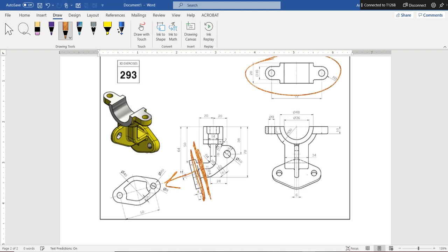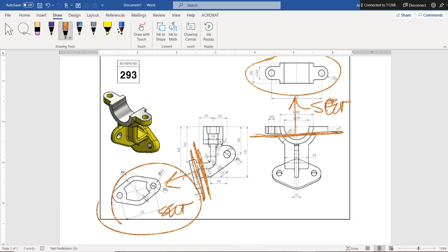Ditto with this thing. This thing should have some type of sectional to tell me that this is only useful when it's a sectional view, okay? A sectional view. Both of these are really sectionals, which are referred to as auxiliary views. They're views that are in addition to the standard views. Got it? In the most generic term, an auxiliary view is a view of a model that's in addition to the standard views.